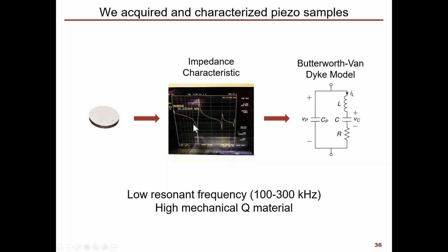Just to give some more details, this is our radial mode resonant frequency. This one would be our thickness mode resonant frequency, meaning the resonant frequency when the piezo is vibrating up and down. Above that, we're getting into higher harmonics of each of those resonant frequencies. One day we would perhaps want to compare, across all of those, the difference between the resistance and the characteristic impedance.